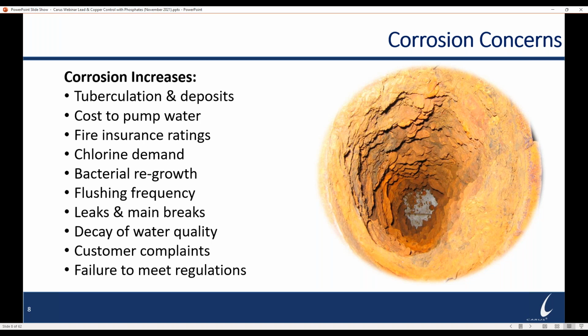One of the things engineers will do is when they're designing a distribution system, they size the pipe in the distribution system based on how many customers and how far they need to transport that water. So as you restrict that pipe, that fights against all the design work that they did up front of carrying the water out to your customers. Now the fire department is typically going out and they're flushing fire hydrants in your community, and they're doing that to determine can they get sufficient water at a sufficient pressure out of a fire hydrant to fight a fire if there's one in the neighborhood. They have to report those numbers in different communities, and that can actually set the insurance rating for homeowners in that community if they have impacted water mains at a higher rate.